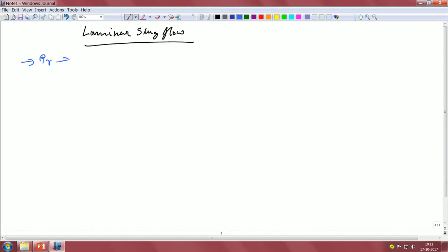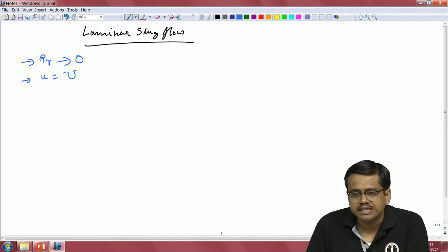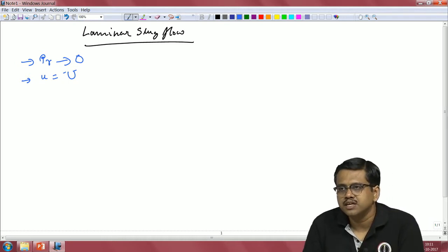We are going to say that Prandtl number almost equals 0. Okay. So, that means the flow velocity at any point is almost equal and uniform to the inlet flow condition, right. So, this also means that the velocity boundary layer or the hydrodynamic boundary layer takes a very long time to develop. So, it does not get developed within the length. So, the entrance length is basically huge.